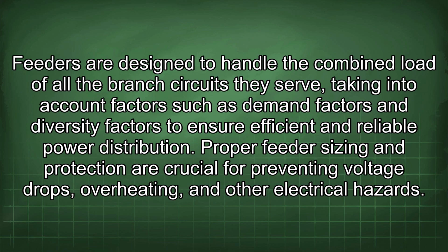Feeders are designed to handle the combined load of all the branch circuits they serve, taking into account factors such as demand factors and diversity factors to ensure efficient and reliable power distribution. Proper feeder sizing and protection are crucial for preventing voltage drops, overheating, and other electrical hazards.